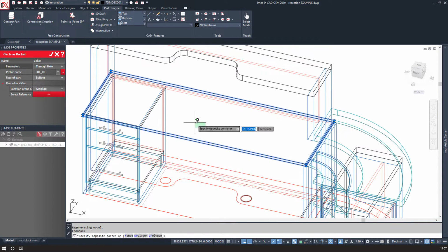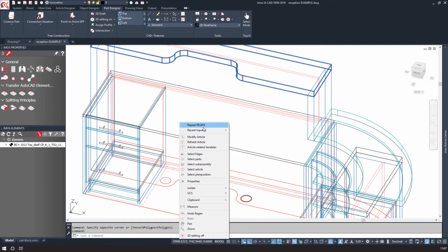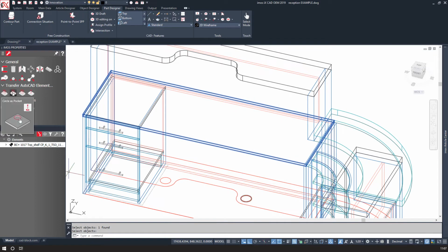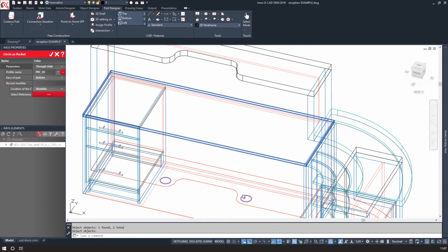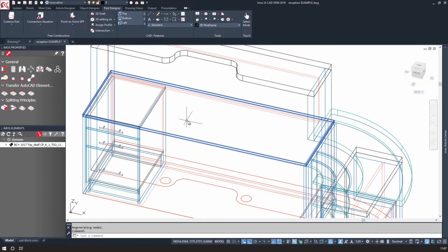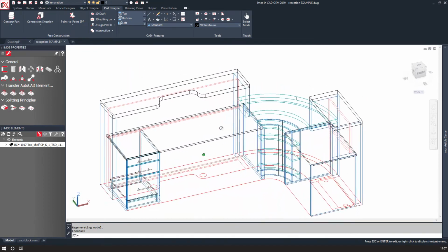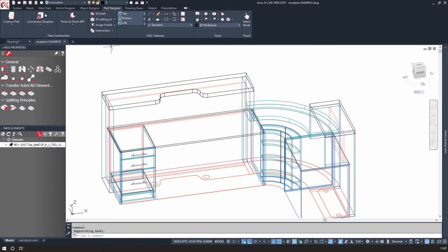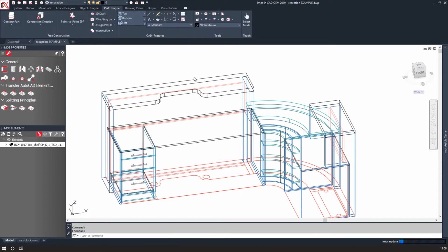And because IMOS can detect the different parts and material and machining features, it will know which machining elements to use certain tools on. It will know that certain thicknesses of machined parts need to have certain tools or feed, speeds, lead in, lead out. All of these elements are based on conditional logic, so it will then automatically create all of the machining data with all of the tooling information automatically assigned.